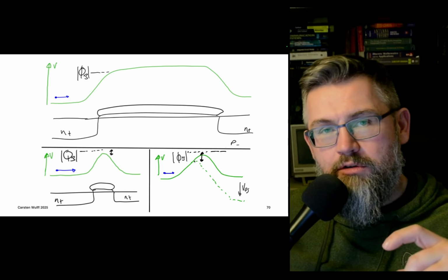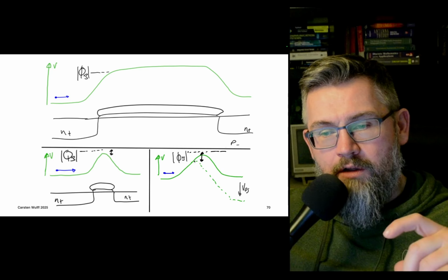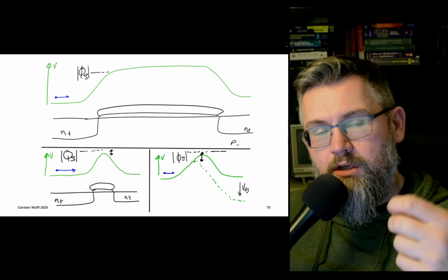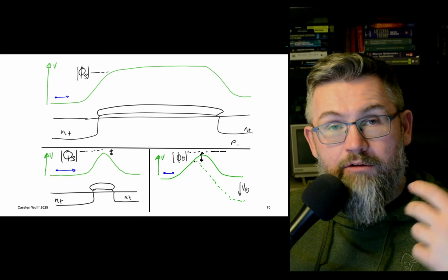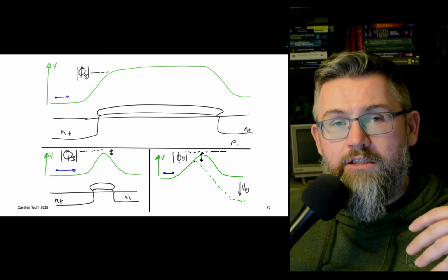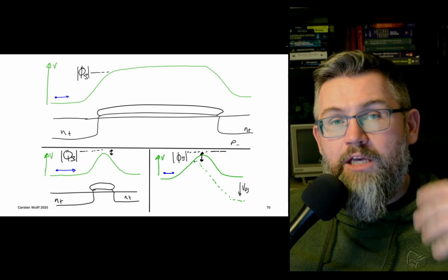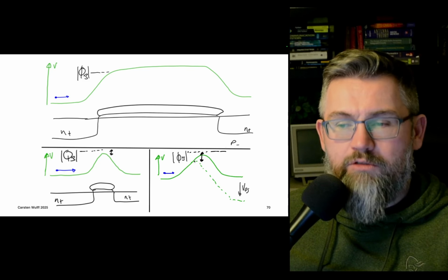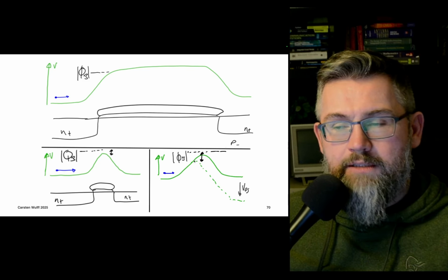So as we modulate the drain voltage, the actual number of electrons that get injected from the source to the bulk increases. And that is the same as a resistor. So as we change the drain voltage, we get more current. So this is, in addition to the channel length modulation, one of the effects that modulates the current as a function of VDS.